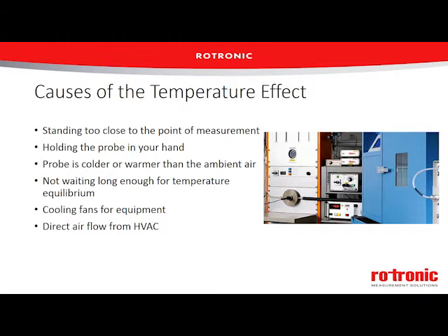In addition to this, we need to watch out for hot and cold spots in our room. So we don't want to put our sensors right next to the cooling fan for a piece of equipment or in the direct airflow of an HVAC system, because both of those will give us artificially high or low readings if we're trying to measure the overall ambient conditions in our room.